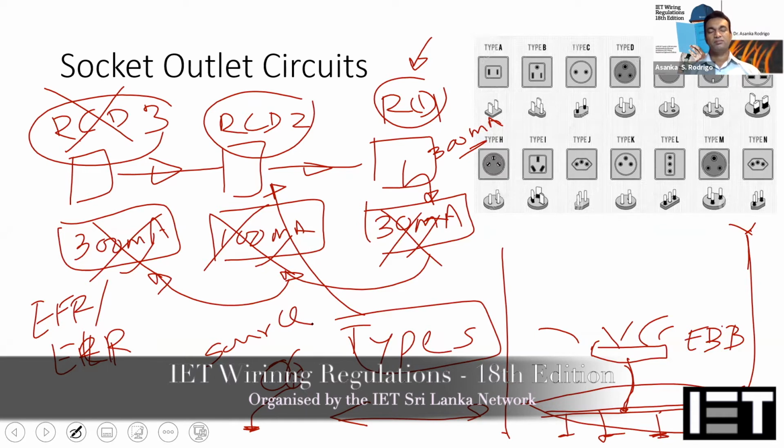Okay. Dr. Asanga, coming back to your point, Dr. Lalit, give me one chance. If you are going for equipotential earthing systems by connecting all the lightning arresters, measuring equipment, and power earthing systems, as per the IEEE regulation there must be a resistance value, maybe below 1 ohm. If the resistance value is below 1 ohm, then we can go for an equipotential bonding system. Is that correct? No, I cannot find where you got this 1 ohm from.